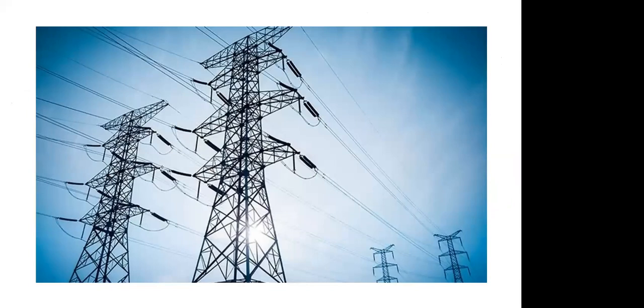These wires must be loosely fitted. If they are tightened, what happens? Daytime these wires expand. Daytime they get heated up, and that is thermal expansion. If they can't expand, then what happens? They get disconnected from these places. That is very dangerous. Thermal expansion, because they are metal.